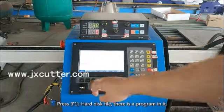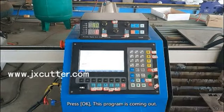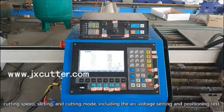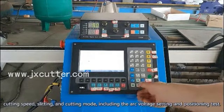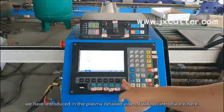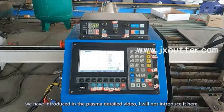Press F1 Hard Disk File, and there is a program in it. Press OK, and this program comes out. Set these parameters after the picture is imported: cutting speed, slitting, and cutting mode, including the arc voltage setting and positioning test. We have introduced this in the plasma detailed video, so I will not introduce it here.